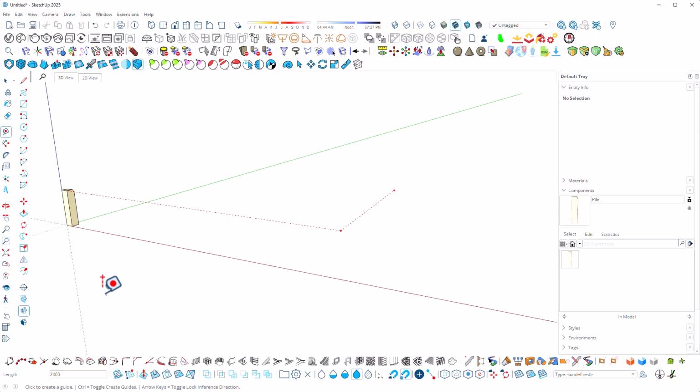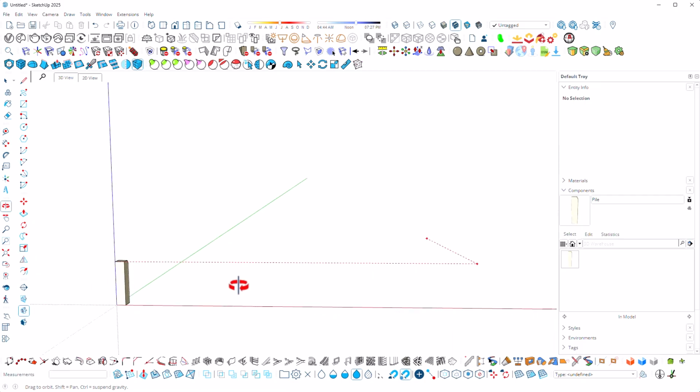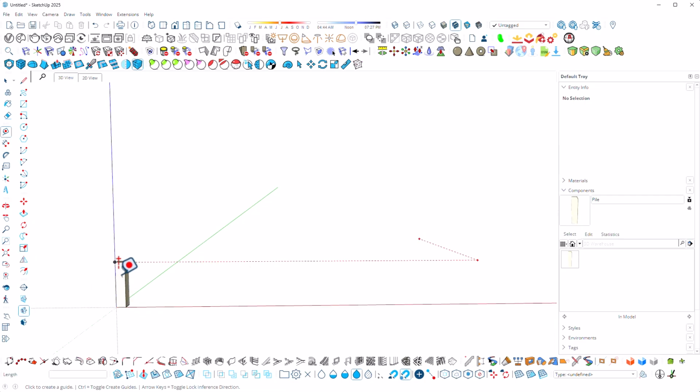Now we have the extremities of our subfloor platform. There's just a couple more things that I want to map out, because we're going to be using 1200 wide plywood and that needs to be supported by something. We need to mark out where our joists are going to lay for the future. So 1200, there will be a joist here. I'll just make some call outs. We won't use these in this tutorial, but they will be there for the next.